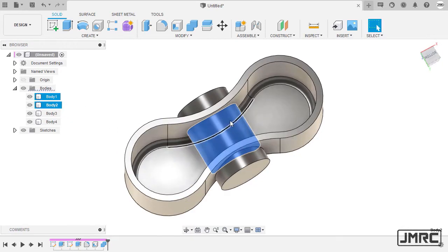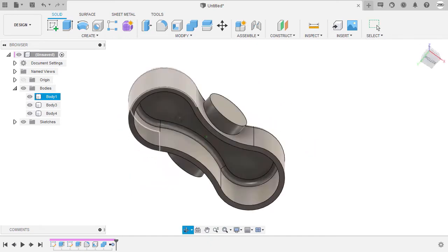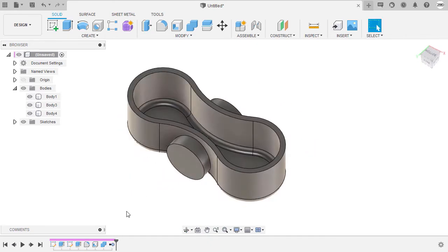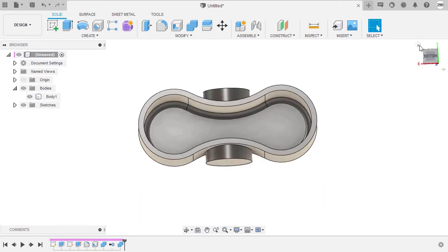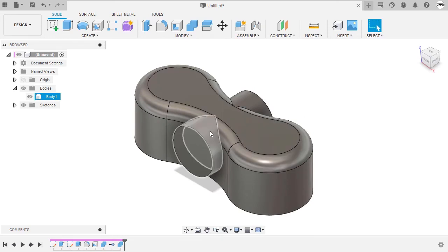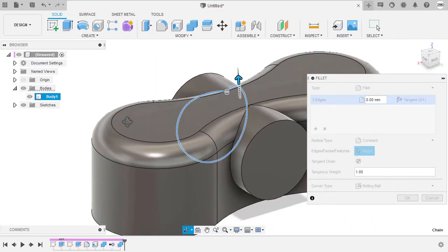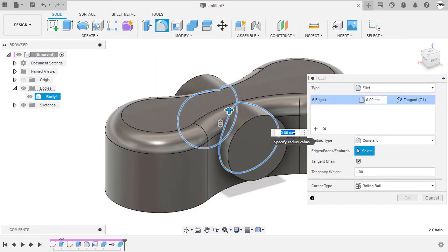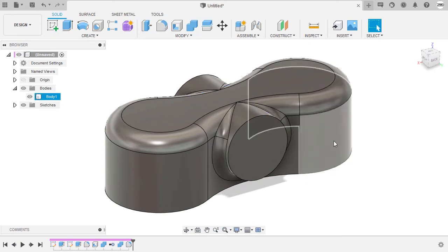Once more, selecting this body, right click and selecting remove. The advantage of a remove is we can summon that removed body by simply suppressing this feature. Next, let's now apply the fillets, hitting F and selecting these edges, radius to be 3, leaving the defaults, selecting OK.